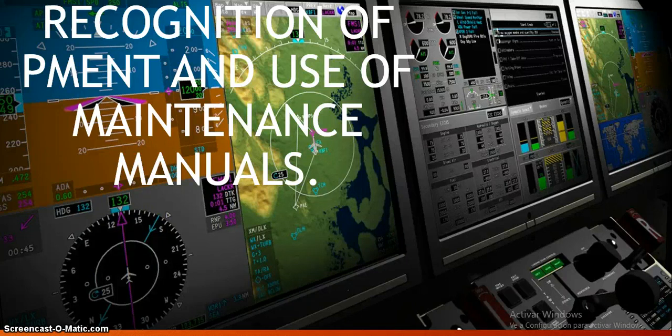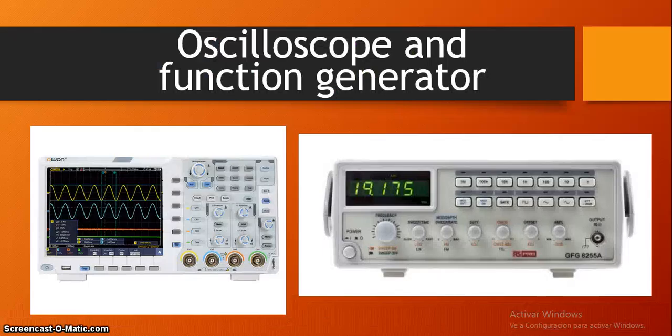In order to measure the signals, we would necessarily use the probes, which are connected to the BNC connectors. The clamp is connected to the ground, while the trailing connector goes to the point of the conductor where the voltage is to be displayed. The probe is selected with a position for 1 and for 10. In the position for 10, the amplitude of the signal is divided by a factor of 10.